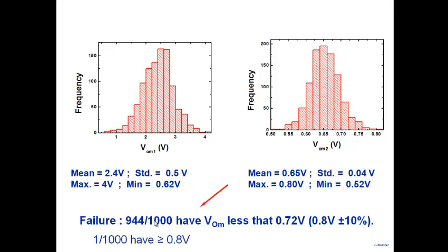My design has to be guaranteed under all these variations, and that is not going to work if 944 of them are going to fail, which is basically telling us that I cannot guarantee those specs under these conditions. Okay, so now how do you do the design with these variations in mind? Obviously, you can't choose certain values, run these Monte Carlo simulations, see what is happening, then tune and run and go back and forth.